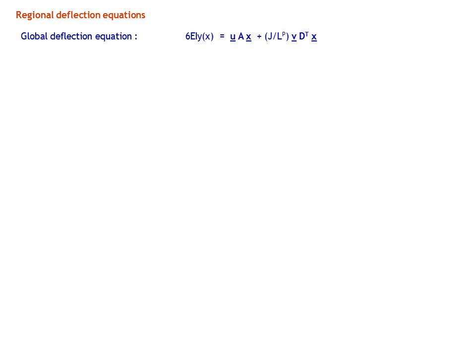Starting to the left of the load, we see from the diagram that x is less than or equal to A, which is the same as x is less than or equal to A_1, as A and A_1 are the same. But looking at the general inequality for x, the upper bound on x here is A_(R+1). For this to be the same as the upper bound A_1, R must be equal to 0. And this is the general condition to the left of a partial load.